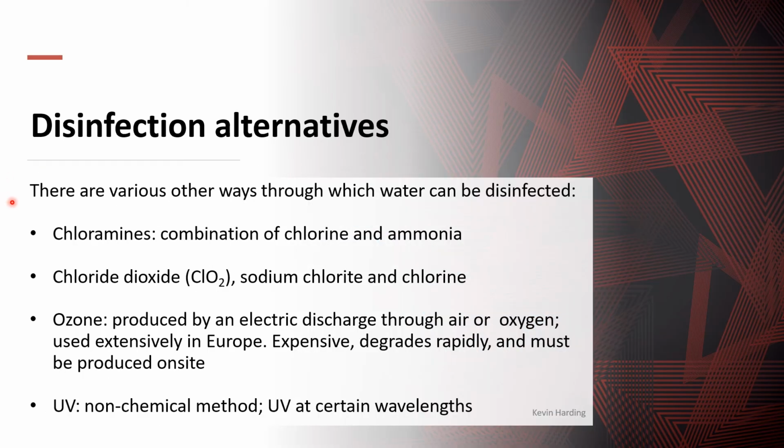There are also some alternatives to simple chlorine disinfection. A lot of them, though, you will see include the word chlor. So they are chlorine dioxides. So it's still a chlorine step, but not chlorine gas, Cl2. 2 other options for disinfection alternatives are ozone and UV. Ozone I have seen being used in both municipal wastewater systems as well as industrial. Particularly if you have an abundance of oxygen, and this needs to be pure oxygen, not air, although air will work.